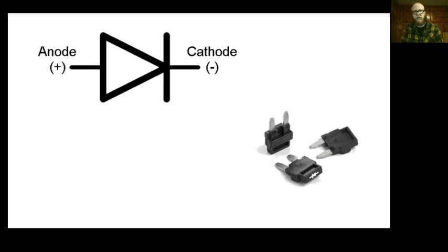Just like our ignition coil, if we make a huge amount of electromagnetism, when we shut it off and that magnetism falls across the coil, a high voltage, thousands of volts, is created and wants to flow in the opposite direction, which means back up towards the switch or the computer that was controlling it. So that diode's there to say, you're not going to get up here and fry this module out.